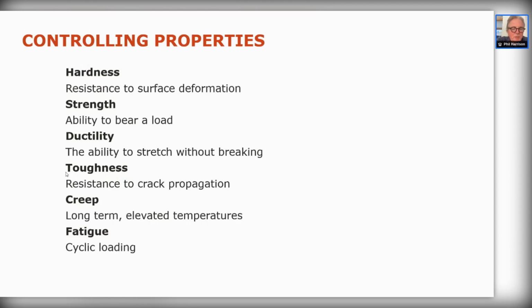And then another property that we look at is creep. Creep can happen at room temperature, but it's mainly classed as an elevated temperature effect. This is where you have loaded a material and it stretches under load, but the load might just be its own weight. It might be a long item which is incorrectly braced, and it could just load and extend and extend.